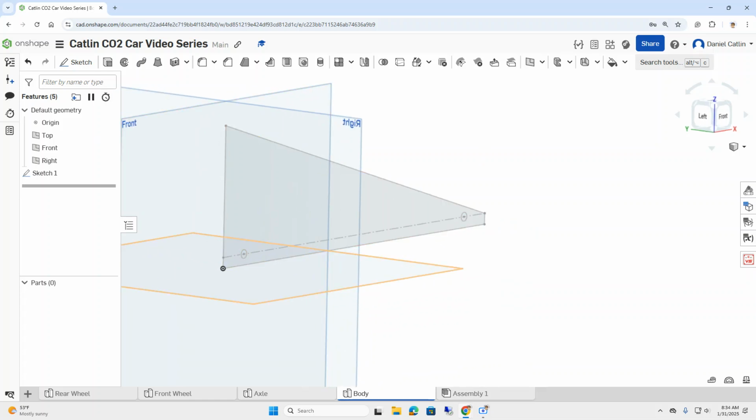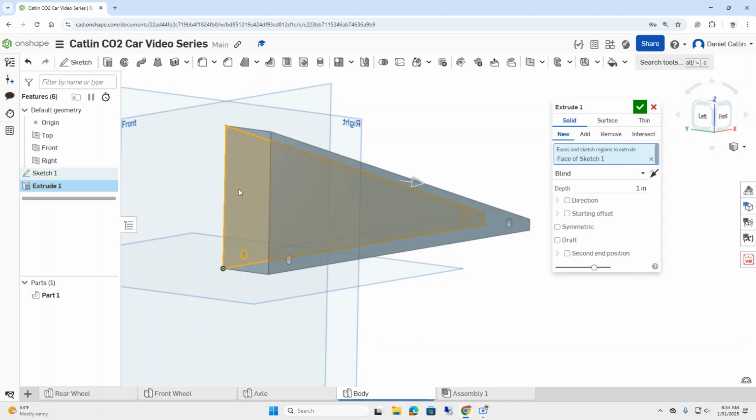The extrude on this particular one, the width that you can look at on your constraint list, you want to extrude this to a certain depth. Make sure that you're creating new material here because this is a new space. Let me check and see what depth I have on this one. I believe I did 36 millimeters, which is the widest that it can be. So I'm going to go ahead and type that in as 36 millimeters.